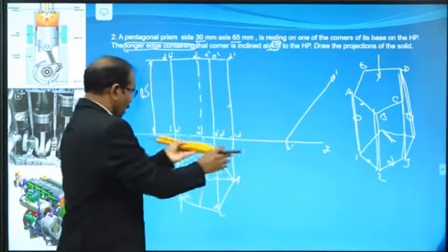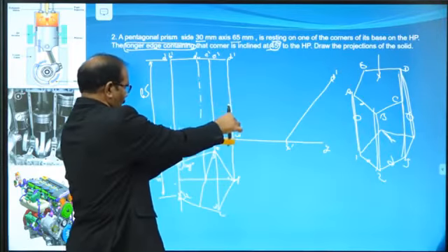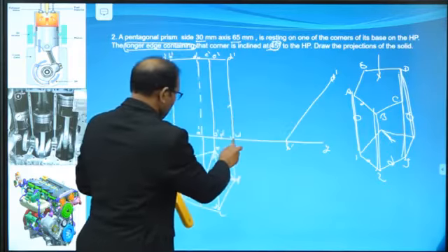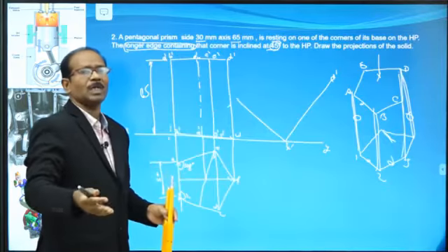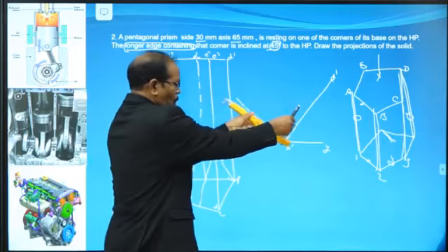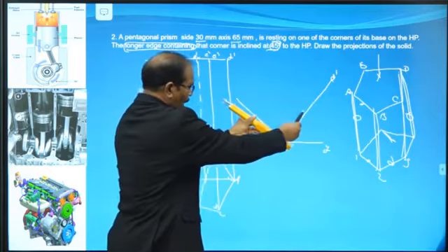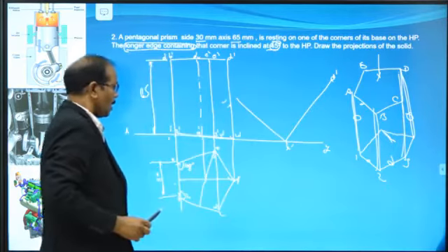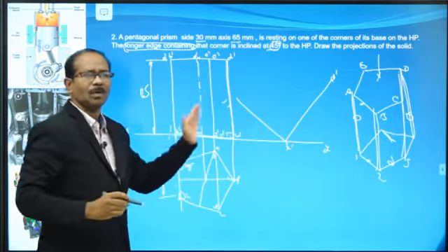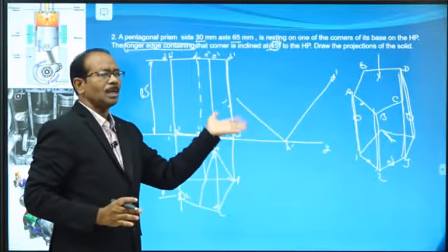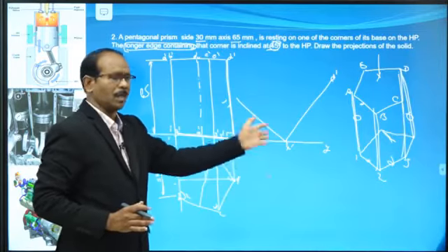Then while moving this one, this edge is at an angle. That means always this is the procedure. This is the vertical edge, this is the horizontal edge. While tilting that one, this line is also tilted at an angle 90 degrees. That is the procedure. Using your mini drafter, while drawing this one, lock your mini drafter edge. Lock it using this scale, draw this line, and using another scale, draw this line. That means these two lines are drawn at a time, always at an angle 90 degrees. You can easily draw this diagram in a faster manner. Lock your equipment and draw.